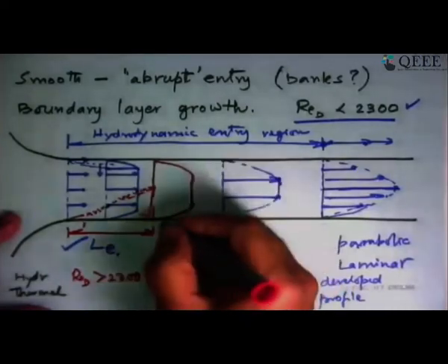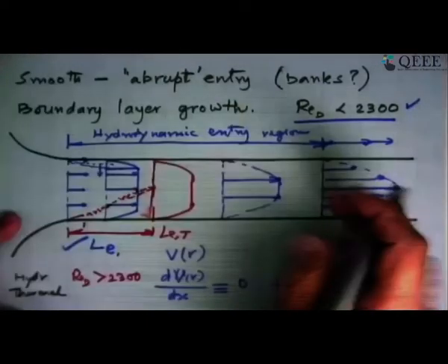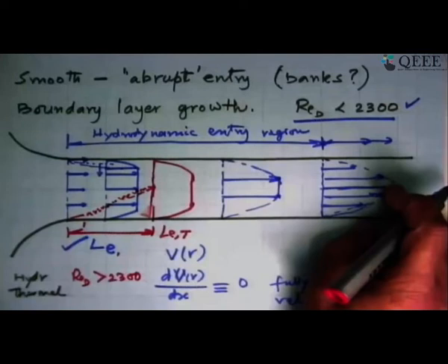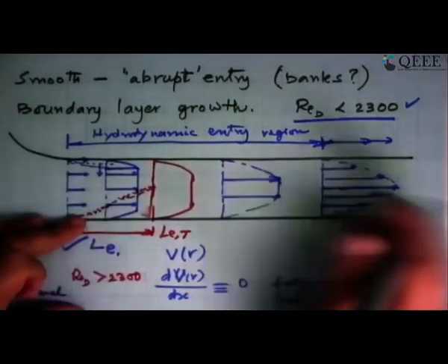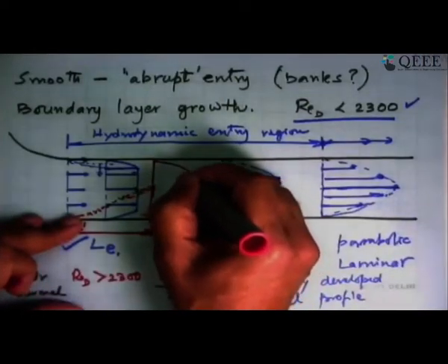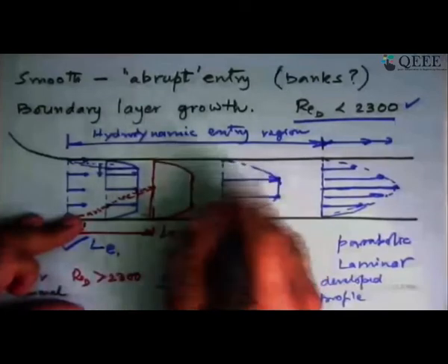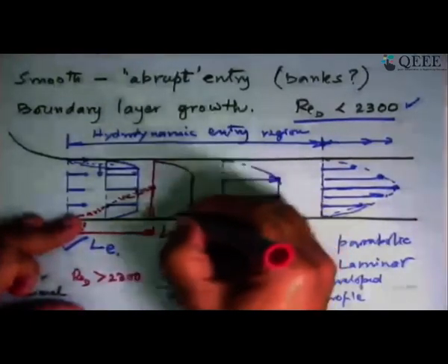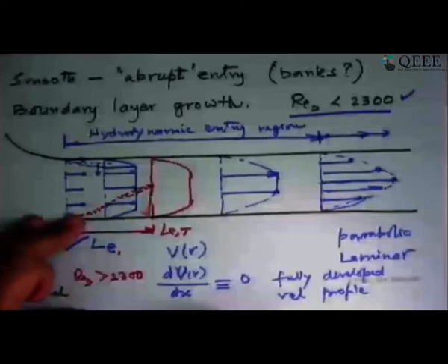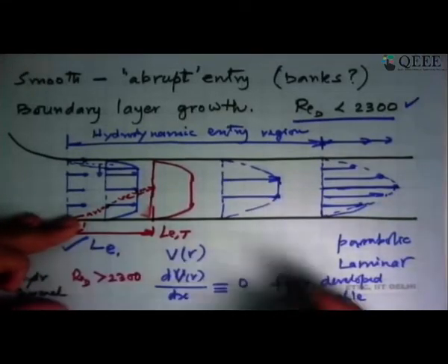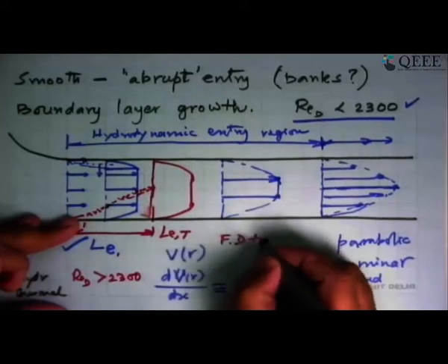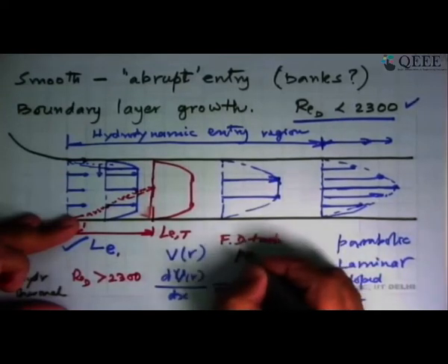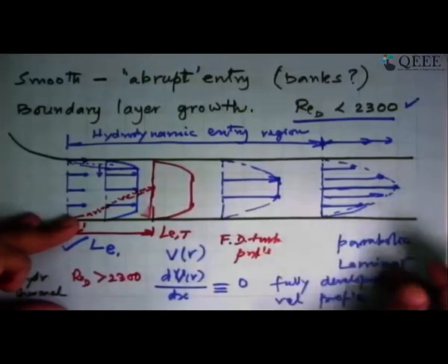And when you say laminar profile, it doesn't mean, like in this case, if you take a photograph, as we saw in those pictures, at one point you get something, at a second point you get another picture, but it's the same, at a third point you get the same. Here you get slightly different things because the turbulent flow, sometimes it will be like this, sometimes somewhere there, but the average of that is what we will get. So this is now the fully developed turbulent profile. And that was the fully developed laminar profile.